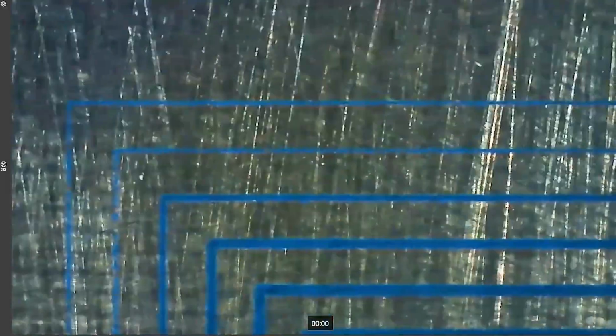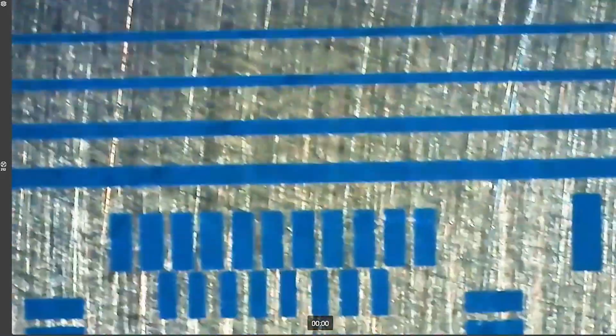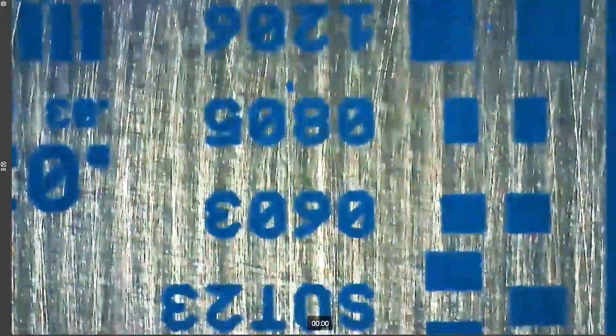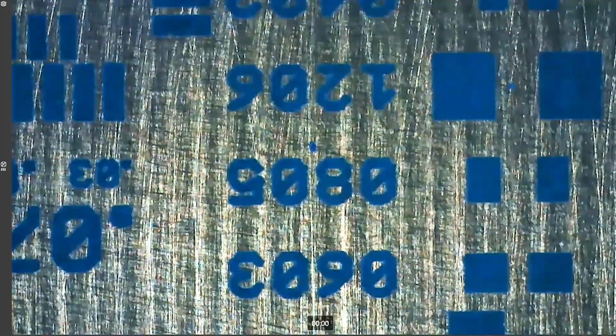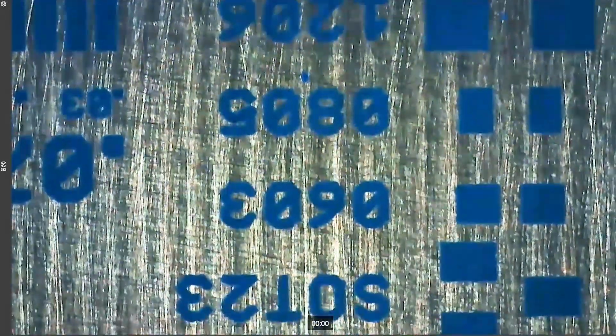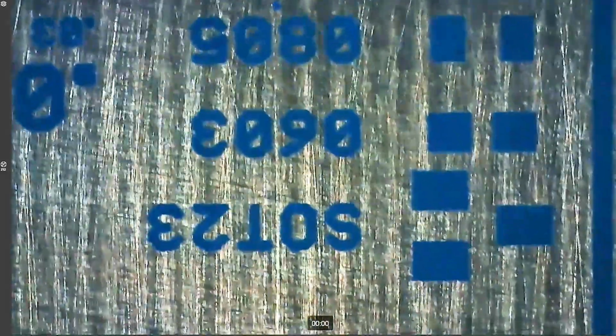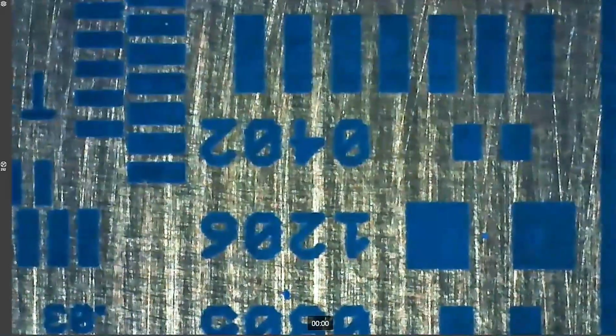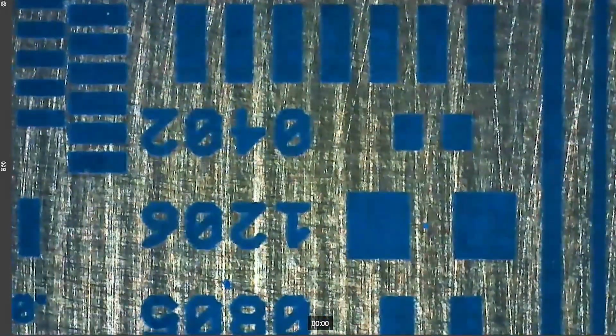I know that people don't like photolithography due to the chemical elements included, but it is the most affordable, very easy technology. Very easy technology. If I can do this effortlessly, of course there are some building blocks of your knowledge, but come on, easy. Small patterns, you know, that 0805 or 0603 easy. Even 0402 you can do.